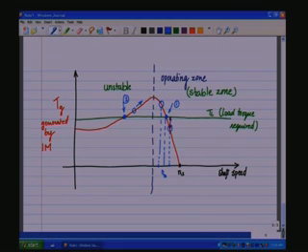So it is not being brought back to the operating point. Likewise, if the operating point shifts here, the speed is lower, torque is lower, it is not sufficient to meet the load requirement, and therefore it will try to stall and the operating point still starts moving further away from the nominal operating point.